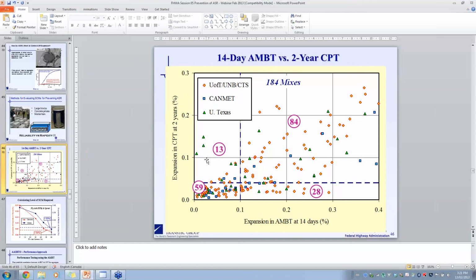You know, that test started off as I think a mix with about 5 or 6 sacks of cement and just, you know, whatever high alkali cement was available in the neighborhood. The cement content and the alkali content of that cement have crept up with time. As I say, the test has evolved, and maybe the next step is to go even higher. I'm not sure if that would resolve the problem, and essentially it will help to compensate to some extent.